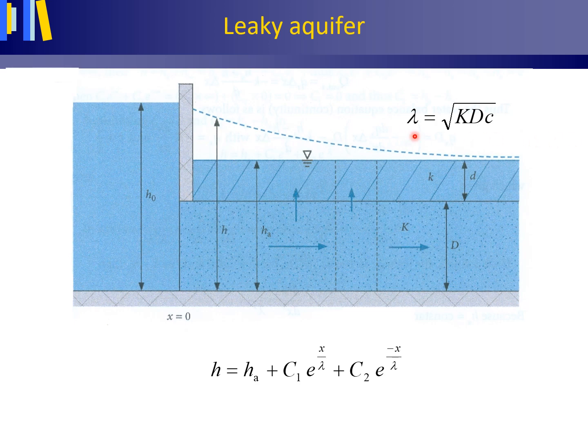Conversely, the leakage factor is small when the leaky aquifer has a low transmissivity, so a low Kd value, and when the hydraulic resistance C of the confining layer is small. Vertical seepage through the leaky confining layer then dominates over the horizontal groundwater flow through the aquifer, and as a consequence in this Holland's profile, the hydraulic head in the aquifer then decreases relatively fast with distance x from the left canal.